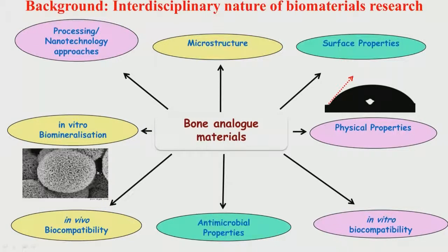This is one of the examples that I have given, where titanium, a well known biocompatible material widely used clinically for different orthopedic applications, is considered. Among the various titanium alloys, titanium 6% aluminum 4% vanadium is perhaps the most widely used material worldwide. From the simple composition, one can perceive that this does not have any hydroxyapatite as a second phase in the microstructure. However, when the same titanium material is immersed in simulated body fluid, it can induce calcium phosphate nodule formation as shown here. These are very nicely arranged nodules several micrometers in diameter.